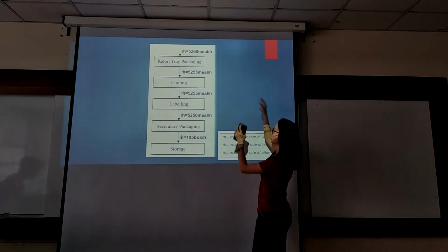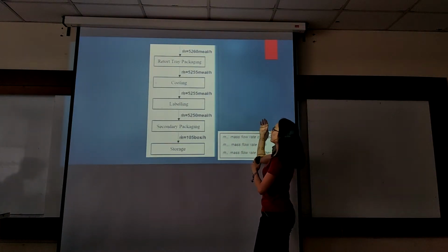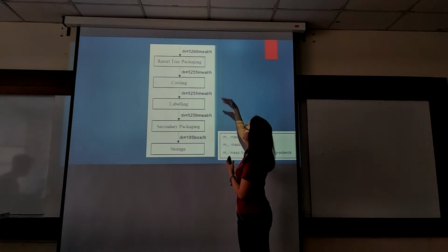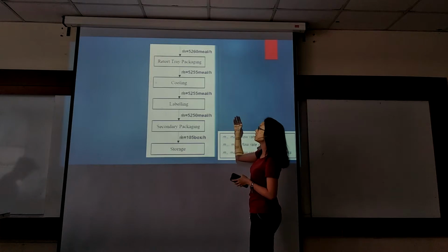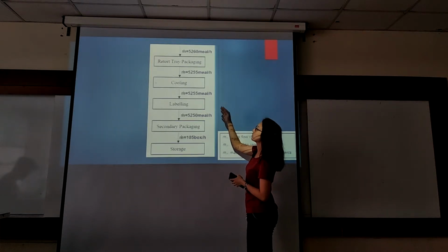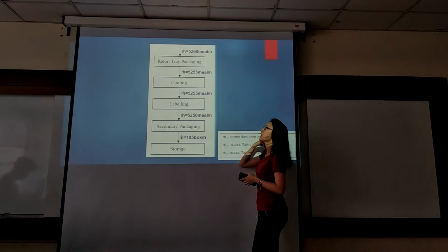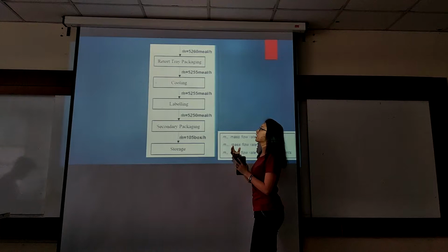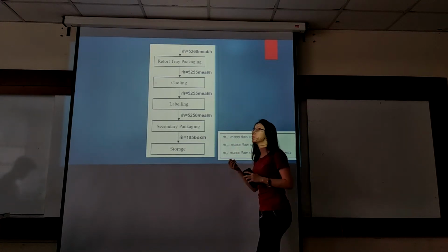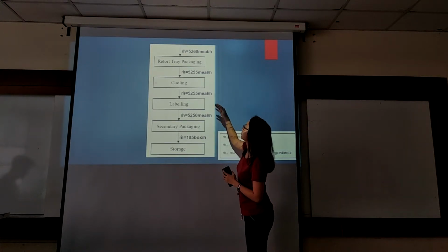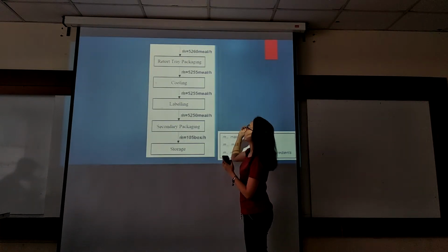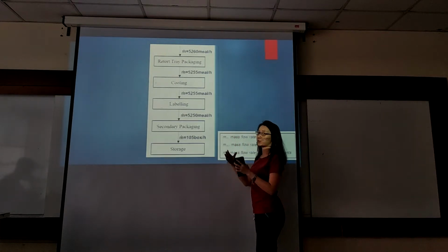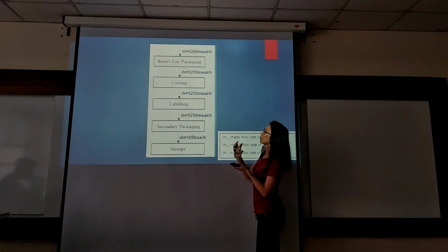Okay, so after mixing the two, the rice and the beef, the total inlet for the packaging process will be 5,260 ml per hour. So the inlet will undergo retort tray packaging. This is the process where we can preserve the food and it can stay for a shelf life of 18 months. So for the outlet of the retort tray packaging, we assume that about 5 ml per hour of the product will have defects, so will be lost.